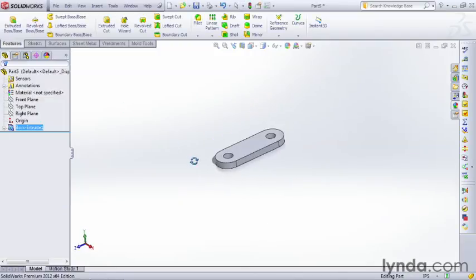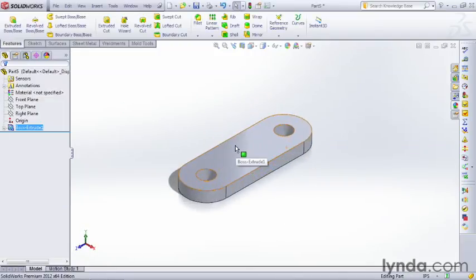This movie combined the line, circle, and centerline commands. We also learned and used relationships together to create a usable part. We also got a first look at the trim and extrude commands. Dimensioning is very important in SOLIDWORKS, and make sure to fully define your sketches with no blue lines, no yellow lines, and definitely no red lines. Now we have a complete part, and this part will be used later in the course.